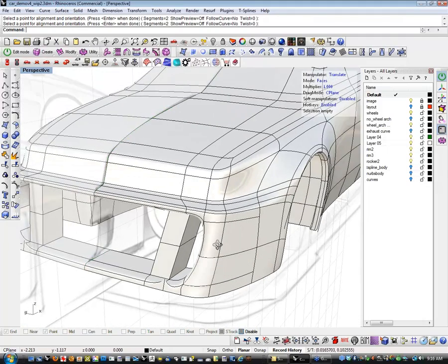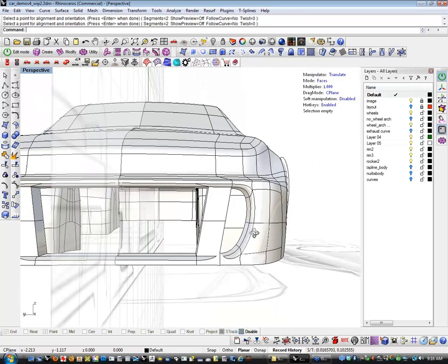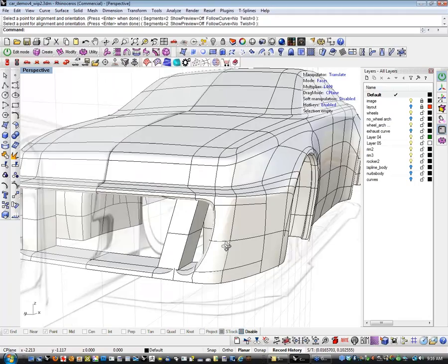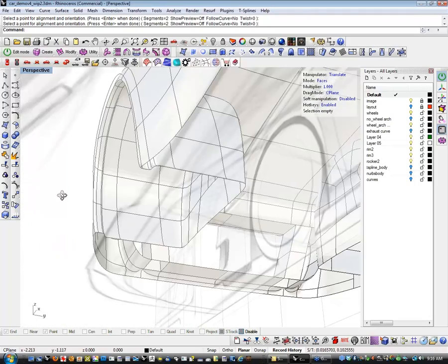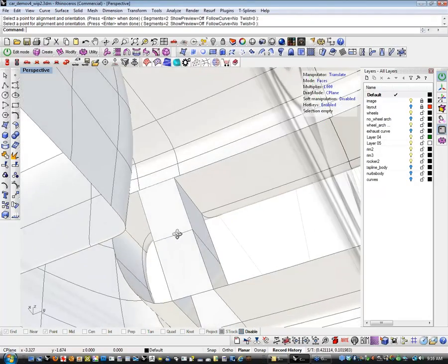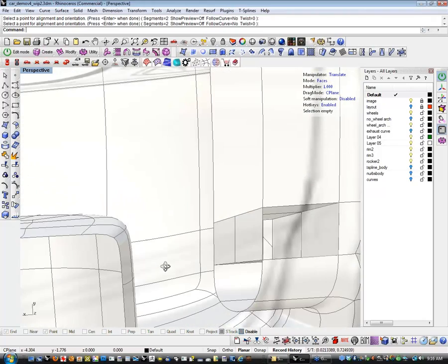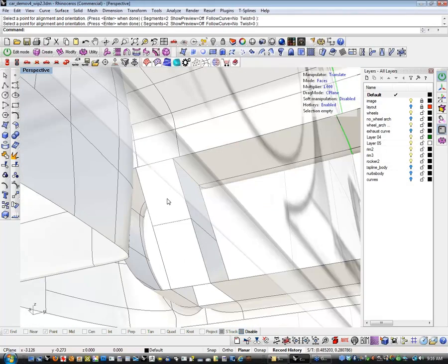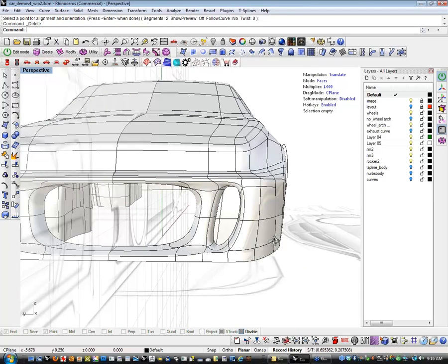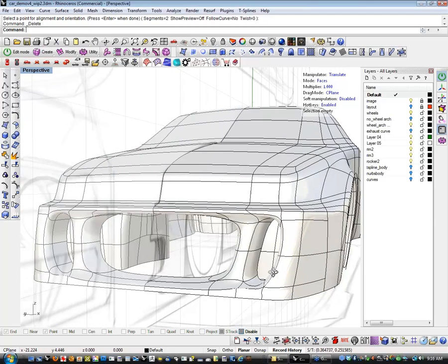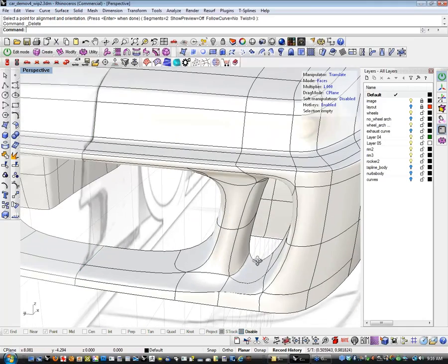So my bridge happened, but it threw a crease and did all sorts of other ugly stuff in here. The reason that happened is when I bridged using a face, it actually put a back on this. And since it put a back on this, it's actually throwing a crease through the rest of the model because of these 2 faces. So all I need to do to resolve that is just pick those 2 faces and delete them, and that'll get rid of the unresolved inside edge condition and allow that to all blend together nicely.